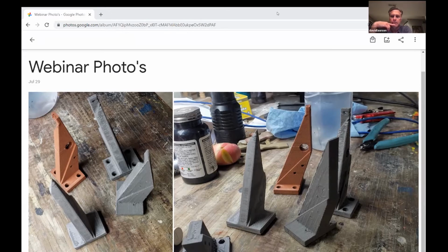And I've done it two ways. I've done it where, just like you see there, there's a blank and then you add the holes or tap them later. Or you print with an undersized hole and then you tap it. I've done it where I tap it pre-sintering, and again, it depends on the shrinkage if you can get that accurately. But if you're just looking for something that's in the ballpark, I've done it that way too. This material is very easy to work with before sintering, and even after sintering, especially the bronze and copper, it's very easy to drill things out.